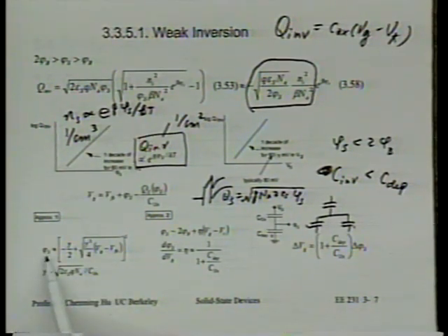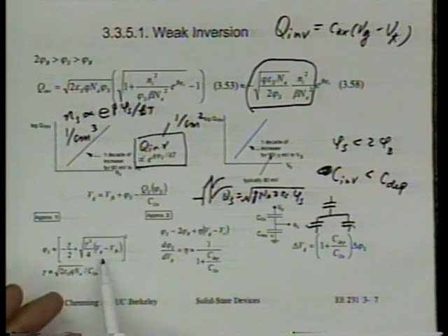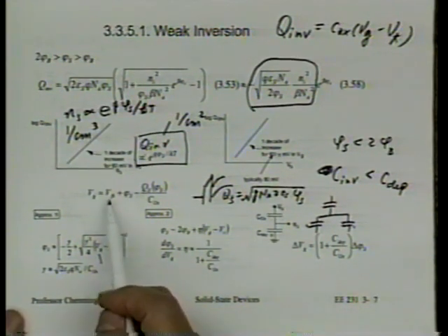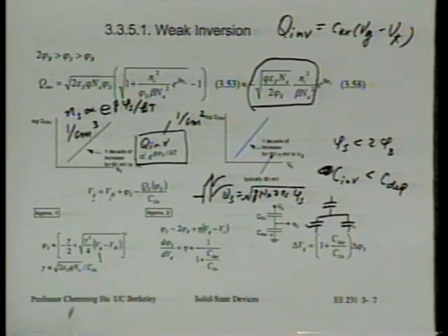Phi s is some square root function of Vg minus VFB. Obviously, it makes sense because the first thing you would do is move VFB to the left-hand side, make that the new variable, right? And in order to solve for phi s, you end up with something like that using the polynomial formula, yeah? Follow what I'm saying? So it can be done that we can find phi s as a function of Vg, but